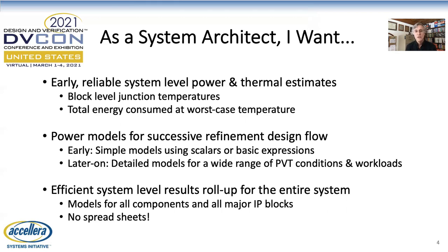So to achieve my goals, I have several wants and needs. Chief among these are early, reliable system-level power estimates and thermal estimates. I want to see, at the block level, power consumption values and junction temperatures. I need to know the total energy consumed at my worst-case temperature, but I likely won't know a priori what that worst-case temperature will be.